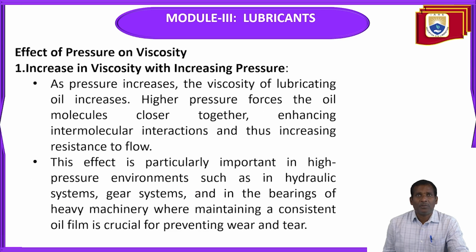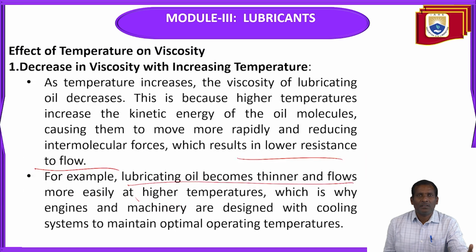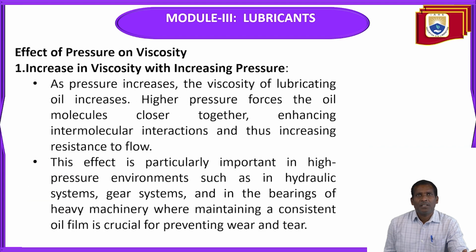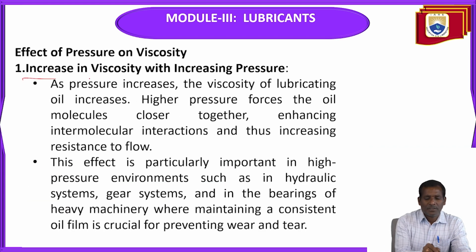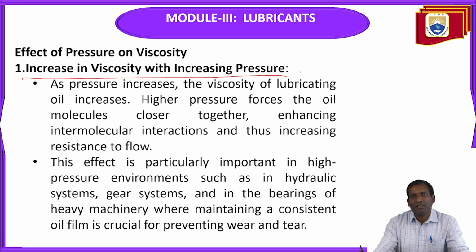Next one is effect of pressure on viscosity. Increase in viscosity with increasing pressure. Whereas in temperature, decrease in viscosity with increasing temperature. But here, increase in viscosity with increasing pressure. As pressure increases, the viscosity of lubricating oil increases. High pressure forces the oil molecules closer together, enhancing intermolecular interactions and thus increasing resistance to flow.